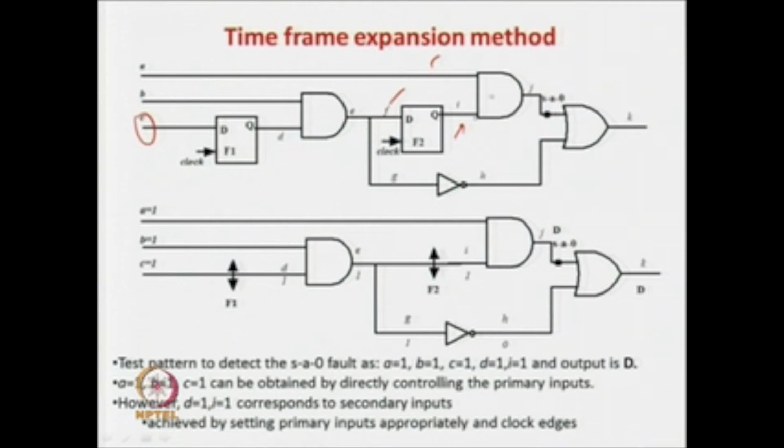Okay. So you can easily map these gates to which is the next state function block and which is the output function block, that can be easily done. But anyway, that is not much of a concern right now. So this is a stuck-at fault over here. So what is the first step? First step is to remove the flip flop. So you have removed this flip flop here, you have removed the flip flop here, and then we have shorted this. So this is your idea.